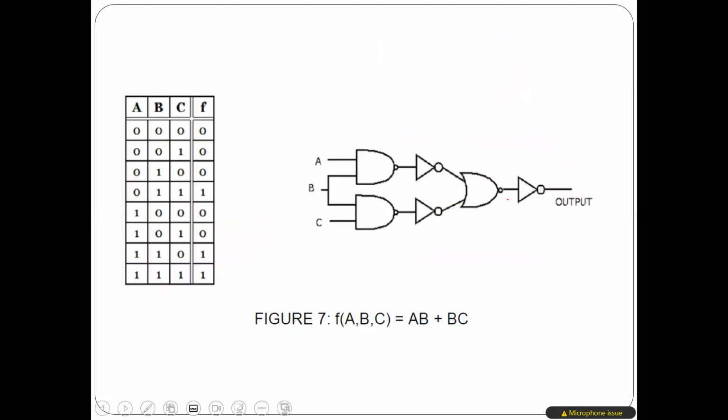Okay? One of the things you have to do in this lab, let's look at this logic circuit here. Very simple. Look here, guys. As I told you in the lecture, this is NOR. And because I put an inverter here, this inverter is going to cancel this one. So these two together become OR. You got what I'm saying?